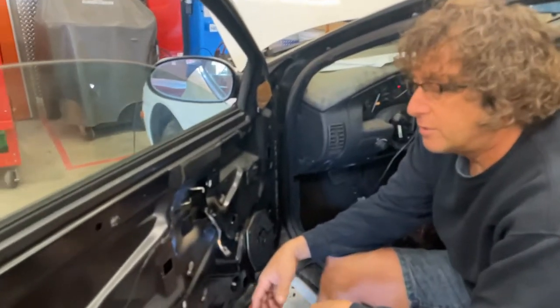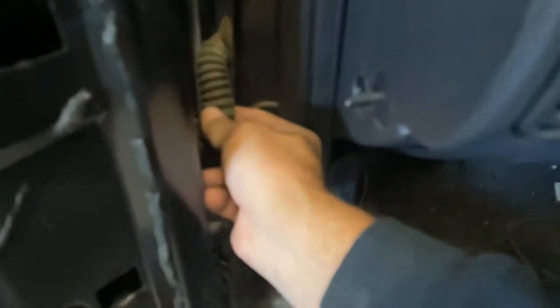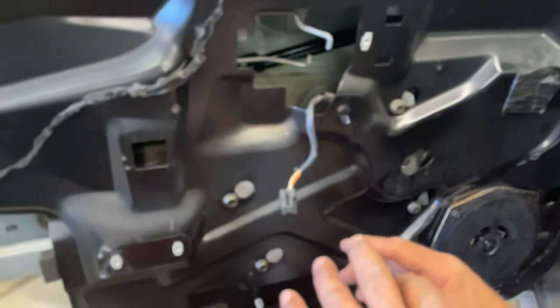So we got the door panel off, and the window motor is actually right here. You can see the back of it. There's usually a pigtail coming out to connect the wires. They travel through this hose right here into the door. But with this particular setup, there is no way to access the motor unless you remove it from the door, and we're not going to do that. So we're going to go back to where the switch is, and we're going to use our power probe to send some voltage to the motor, just to show you guys how you would test out a motor.